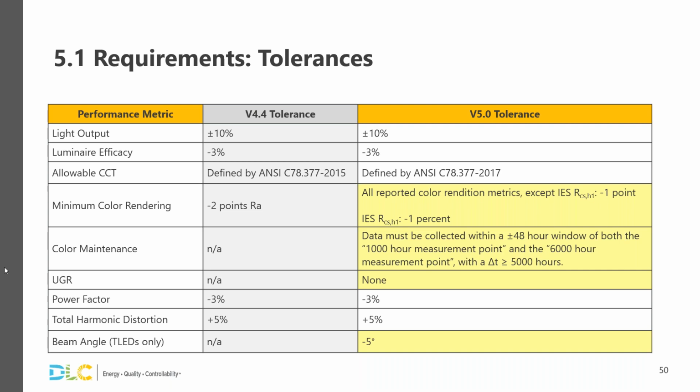Actually, there was a question here about premium that I can address. It's a question about if the 4-step CCT requirement and the UGR requirements in the premium category under 5.1 apply to outdoor products. So the chromaticity requirement, the 4-step CCT, does apply to outdoor products, but UGR, the discomfort glare requirement, only applies to certain indoor product categories that we had on the slide earlier. So those were the troffers, linear ambient, low bay, and high bay. There are no discomfort glare requirements for outdoor.